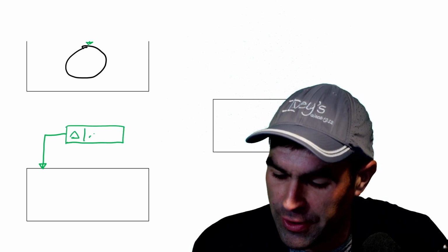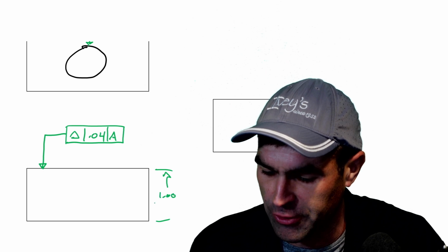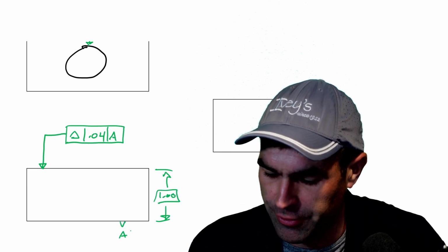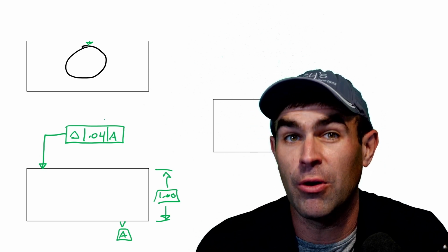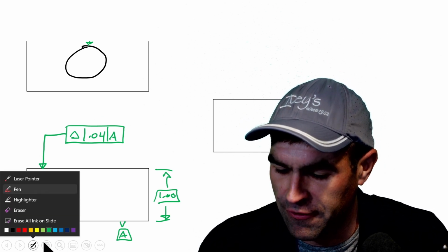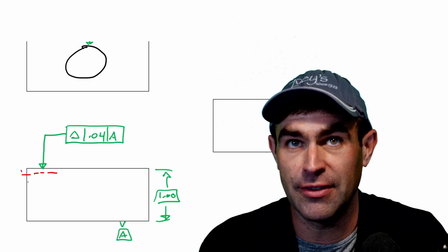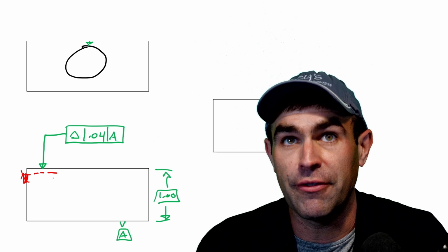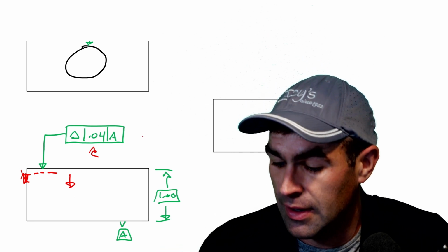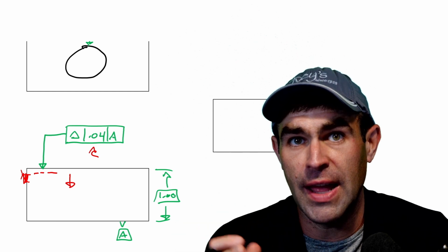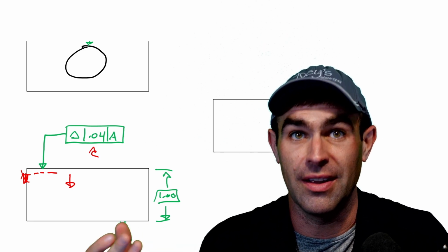We have our feature control frame. Our feature control frame is going to look the same, right? There's no extra information in the feature control frame. And I'll put this over here so I don't get in the way. Okay. In order for a unilateral profile, we're going to put a phantom line either on the inside of the part or the outside of the part. And I didn't give myself a lot of room here, so just ignore that a little bit. So if I put a phantom line on the inside, right, this entire 40 thousandths applies into the part. It'd be equivalent to having a unilateral tolerance in this case, or unequally disposed tolerance in this case of 0, right? 0 of the total tolerance adds.